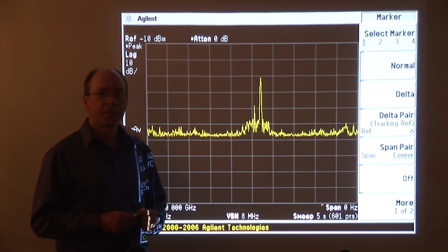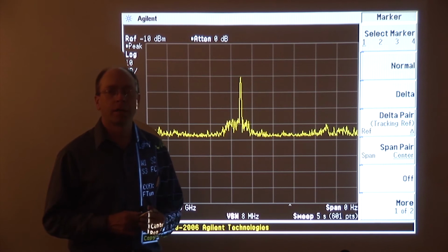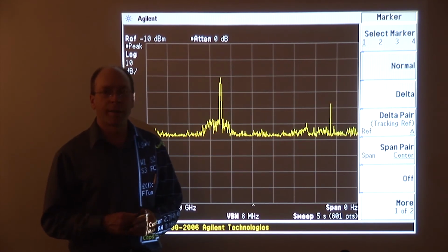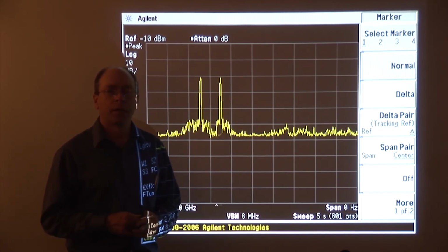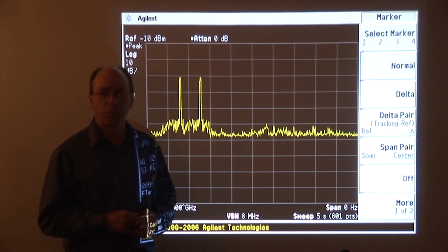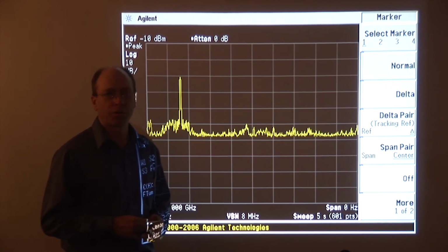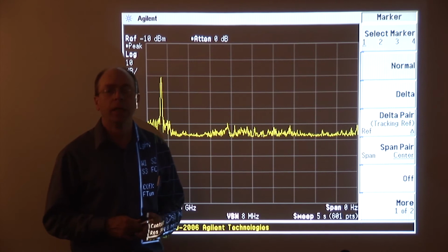All right, this begins the lab session for talk number 9. This is where we will demonstrate the collection of a set of parameters on a radar emission. The parameters that we're going to look at will be the type of beam scanning the radar does, the time that it takes the radar to do one complete beam scan, the pulse sequencing in time, a measurement of the pulse width, and then finally a measurement of the radar's emission spectrum.